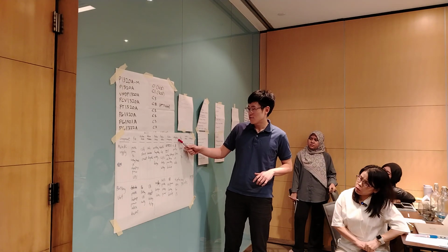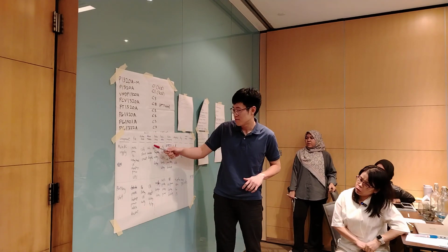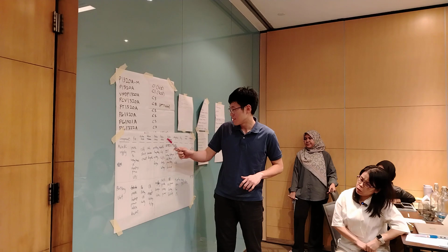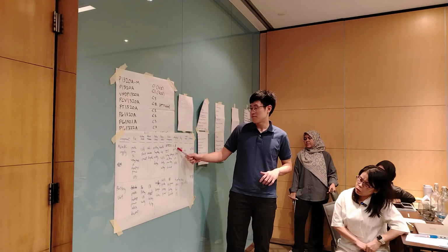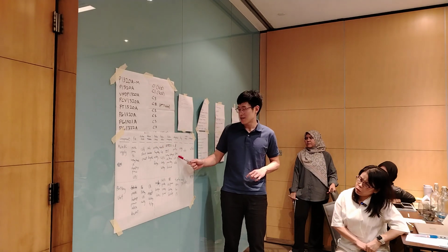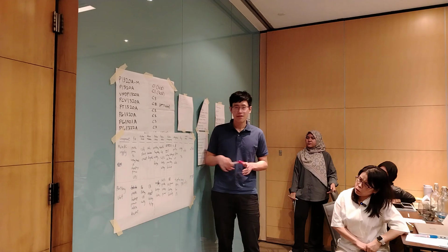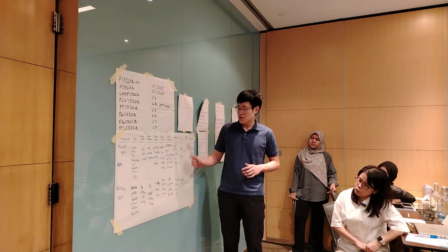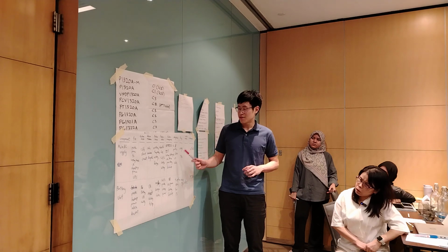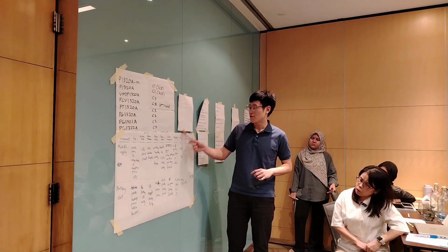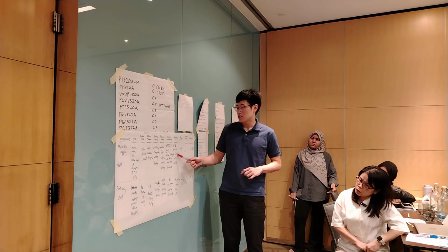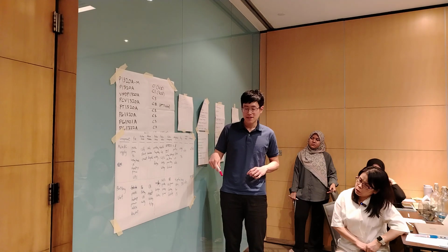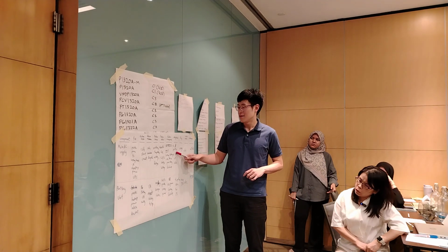So what can we do to prevent the failure? We can perform condition-based monitoring on the cable. Because it's underground, and theoretically a cable is a very, very stable device, we will only perform condition-based monitoring after 20 years of usage.